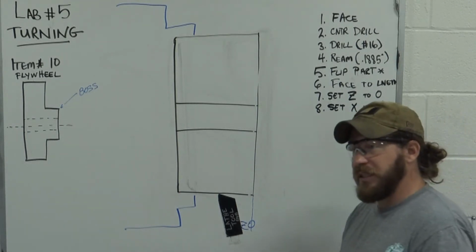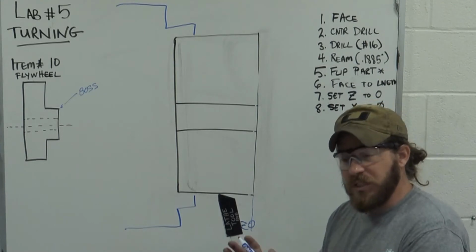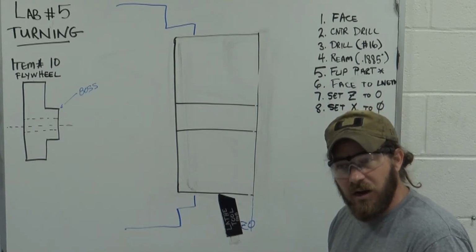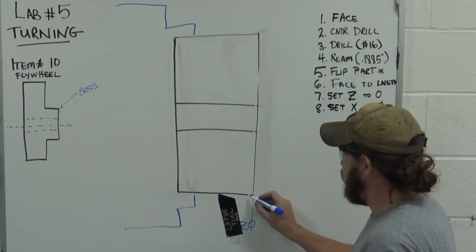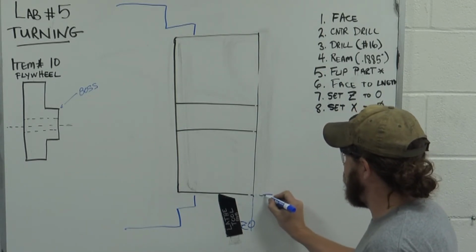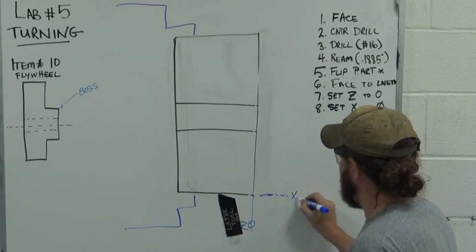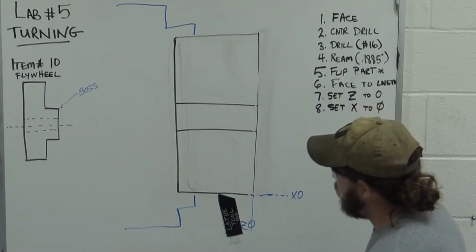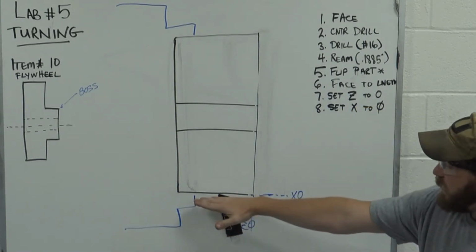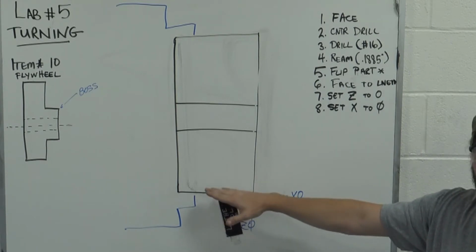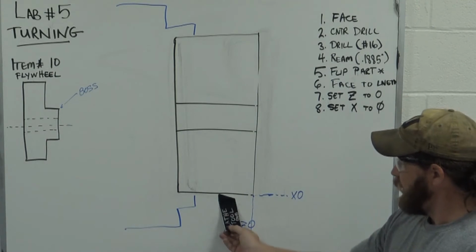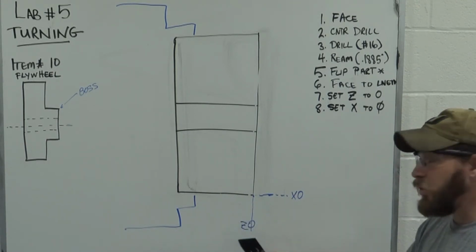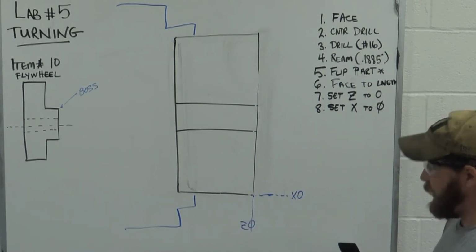And when we just barely touch that outside diameter, we stop, and then we can set our cross slide dial to 0. All right? And what that does is that creates the outside diameter as another datum. Now, we can take our tool and get it out of the way.